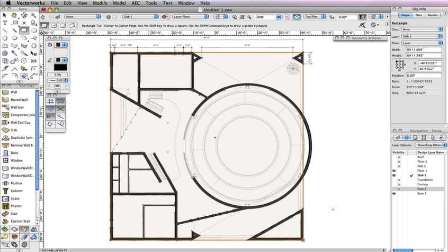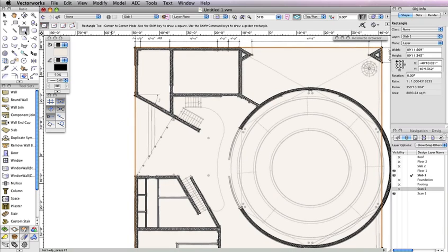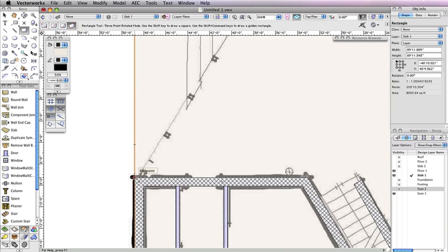You'll also notice that the rectangle extends past the building walls near the building entrance. Let's take a second to fix this. Again, select the Rectangle tool in the Basic Tool palette, but this time choose the last mode. Now, you'll need to use the scan of Floor 1 to snap to the point where the window wall at the entrance and the horizontal wall below that window wall meet. After locating this point, click to set the first point of the rectangle.